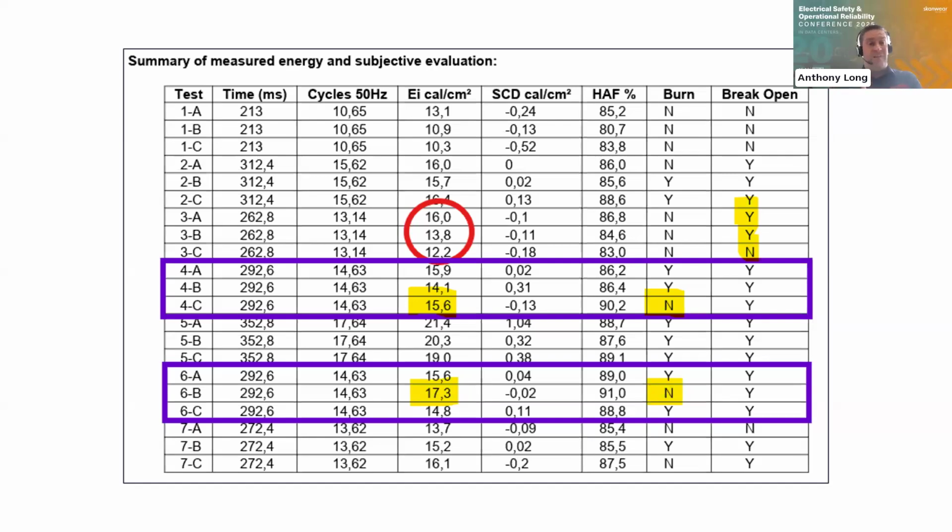Plus, when we test fabric, we're testing fabric directly on the actual heat sensor at the back, which is picking up how much heat comes through the fabric itself. Unless you're wearing underwear, no garment you wear will be so tight to your skin that there is no air gap. When we do dual layer tests, there's air gaps, which is why we often see a spike in the actual arc flash ratings. So where you might say, I've got a 10 cal garment and a 10 cal garment, and I'll achieve 20 cal, because you've got an air gap in there, often you'll end up with a higher cal rating. Obviously, not always.